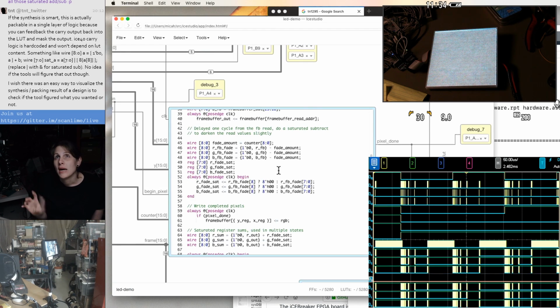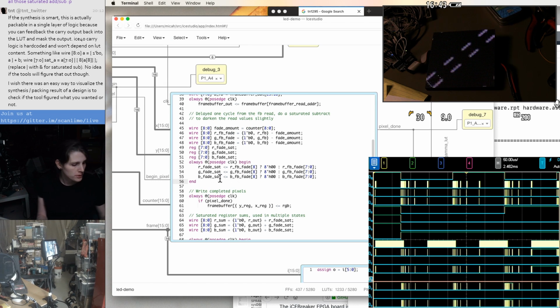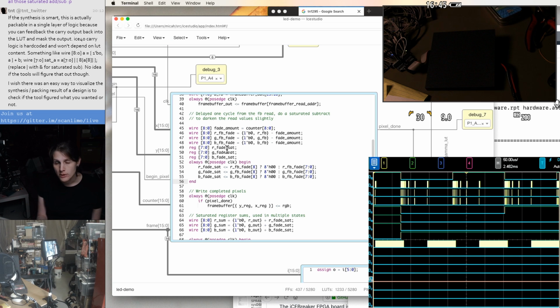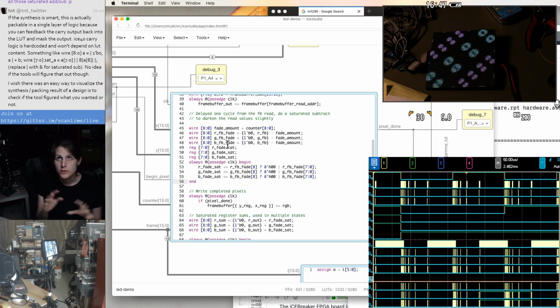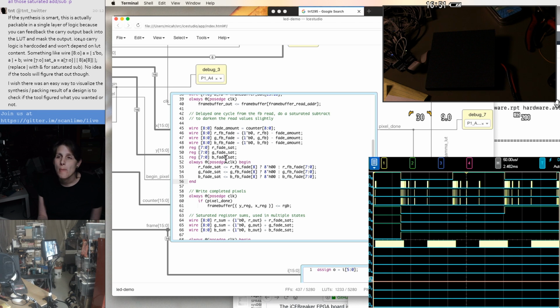I was having trouble balancing it because either it would saturate to completely white or it would be so dim that the blurring was no longer showing up really. I need to do 2 8x8 multiplies. So I could use 2 of those DSP units. Or sorry, 3 8x8 multiplies, so I could use 2 of the DSPs configured as 8x8s.